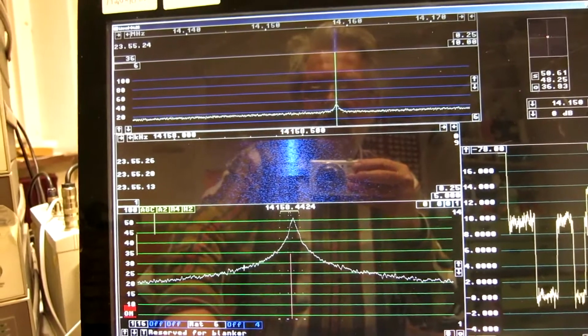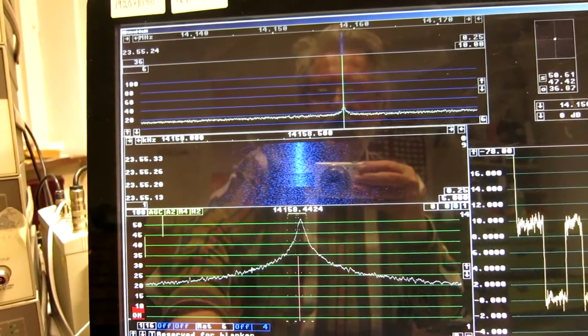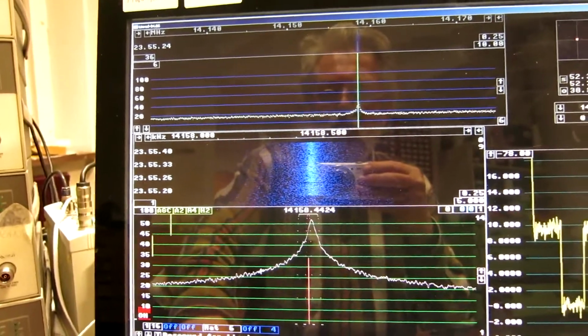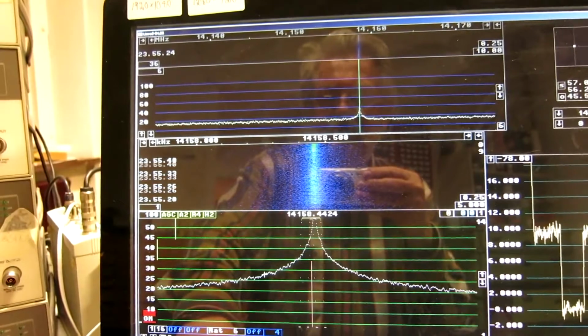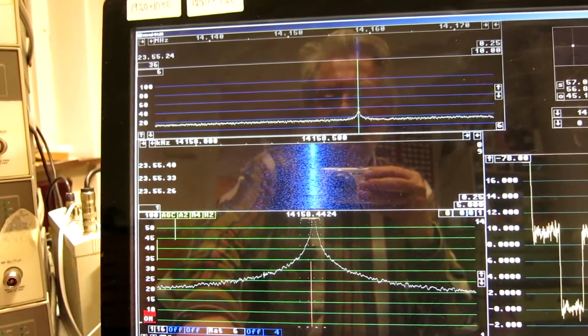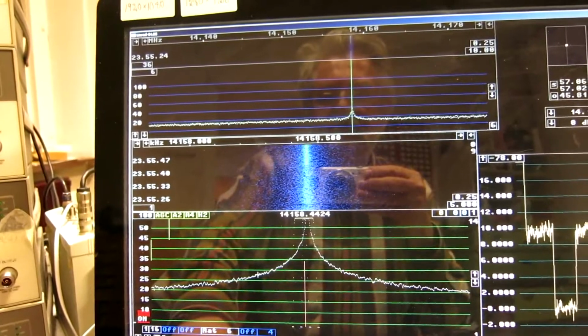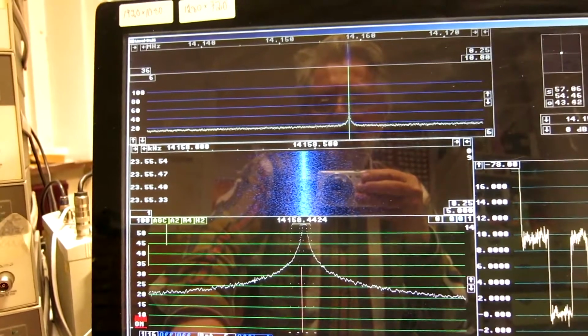And the noise peak becomes sharper, but the noise at 200 Hertz does not increase. So 1 more decibel of feedback. And now the noise peak is rather narrow.